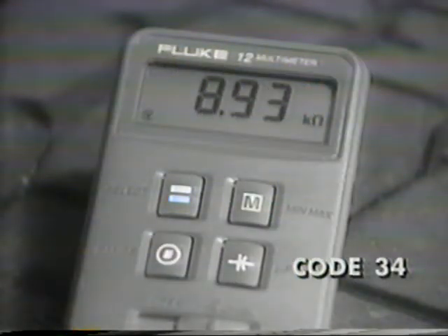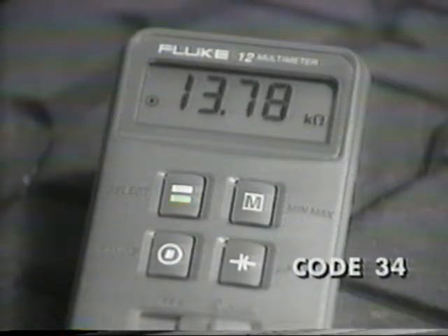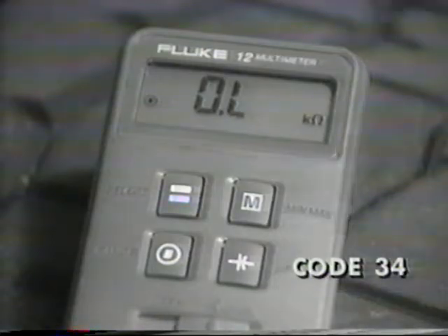Resistance should increase smoothly. With the probes between terminals C and B, move the throttle slowly again. Resistance should decrease smoothly. The resistance between terminals C and ground should be open. If any of these readings fail, replace the sensor. If the sensor is okay, check the wiring harness.